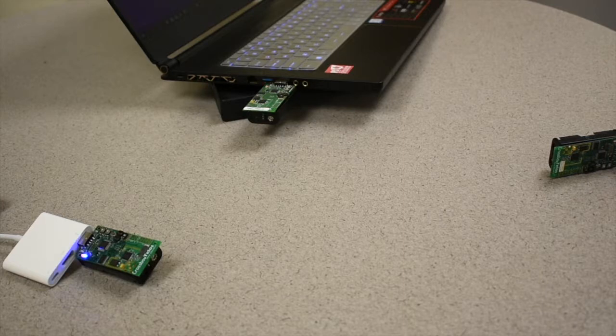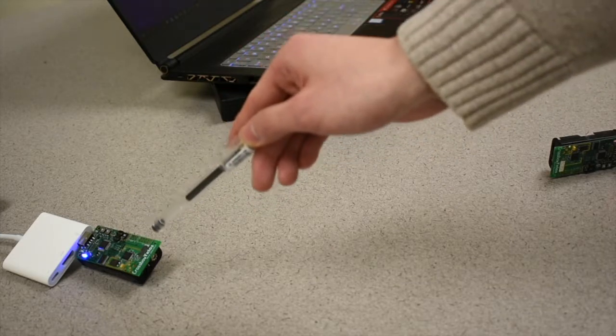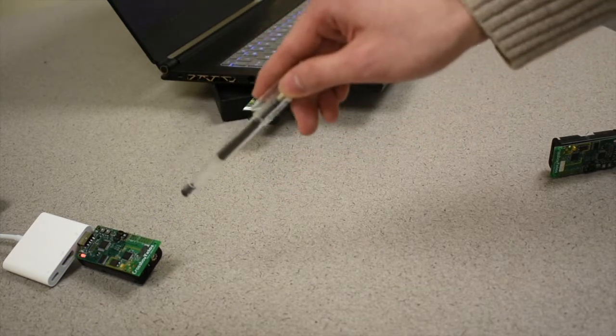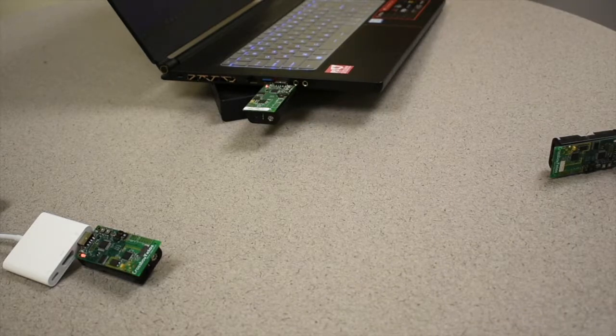But due to the limitation of the transmission distance, we can't let this simple network work in multiple rooms or collect outdoor temperature. So we developed a tiny multi-hop wireless sensing network. One node sends data packages to the relay node. So this one sends the data packages to the relay node, and then the relay node will take the packages and resend them to the base station. So based on this wireless sensing network, the maximum transmission distance doubles and the whole system can be more efficient. Then I will demo this to you in this video.